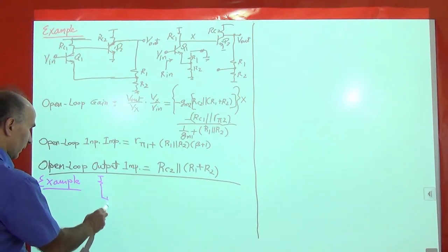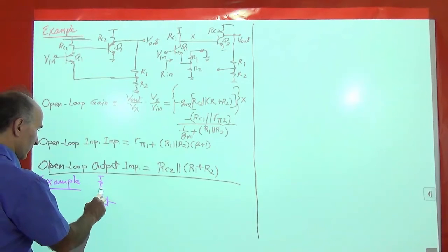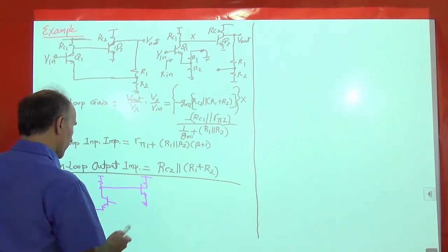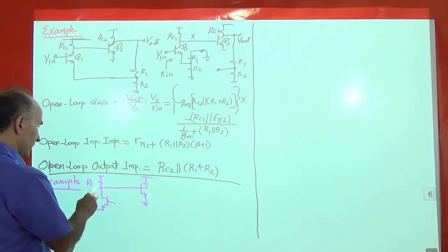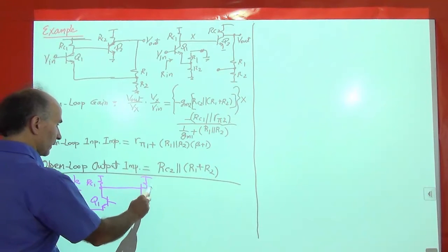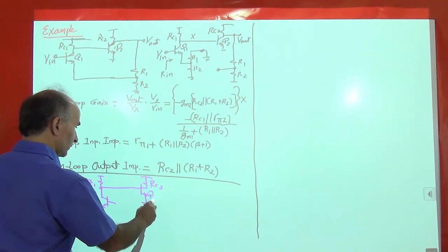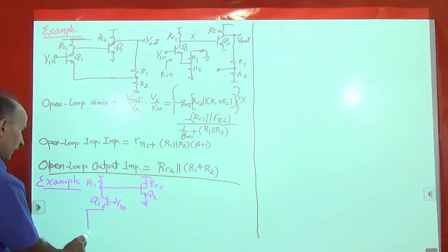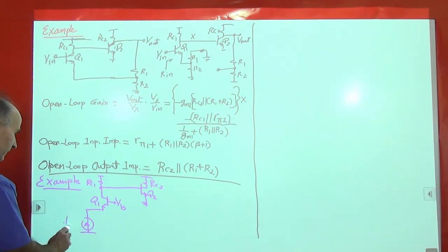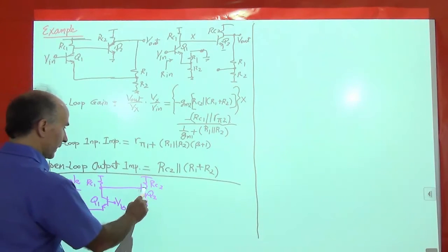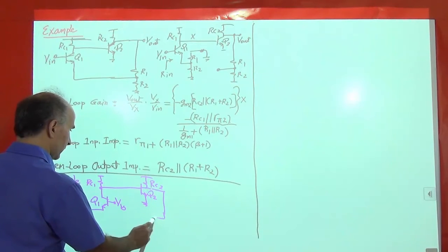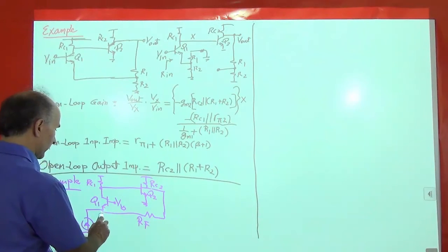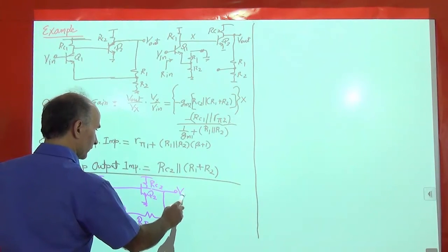So here I have a circuit like this, and I have a 2-stage amplifier, RC1, Q1, RC2, Q2, and actually I have an input current, so I'm trying to build a trans impedance amplifier. I take this output and just connect the resistor between the output and the input. So my feedback network consists of only RF, and that's the output voltage.